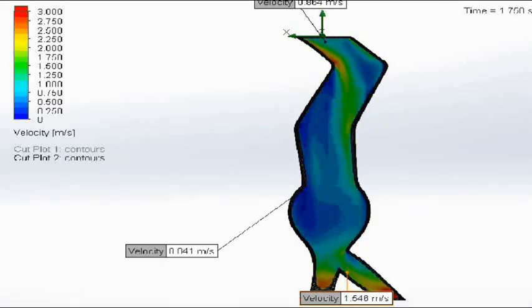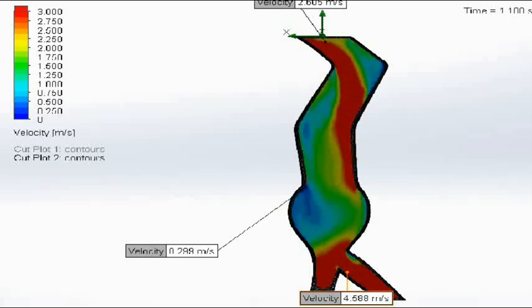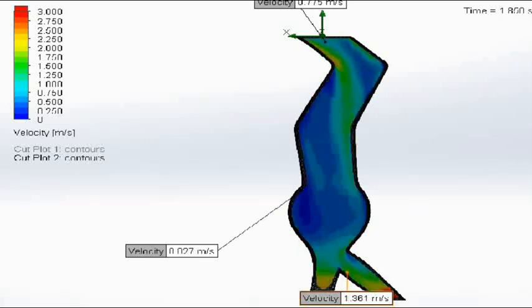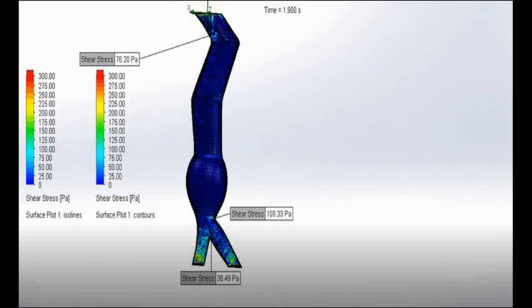Contrary to what Suzuki said, the regions with the higher wall shear stress were the ones that had the aneurysm, and it also had a higher velocity. The aneurysm model in this particular study had an outlet velocity of 4.3 meters per second, being one of the highest velocities throughout the study, and having a direct relationship with the wall shear stress.